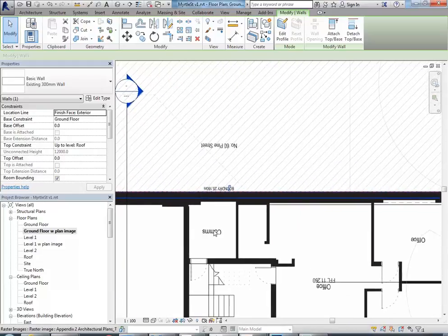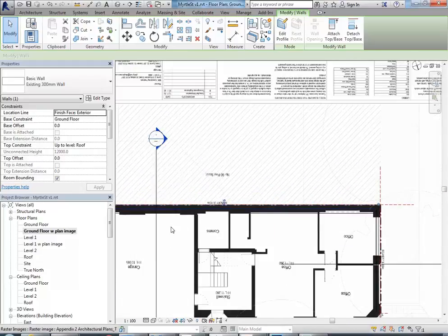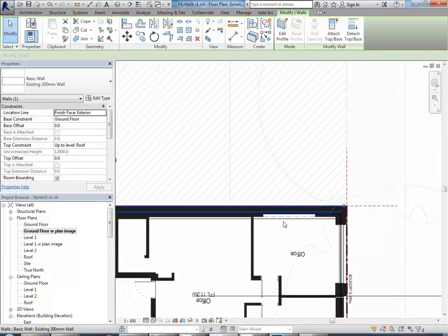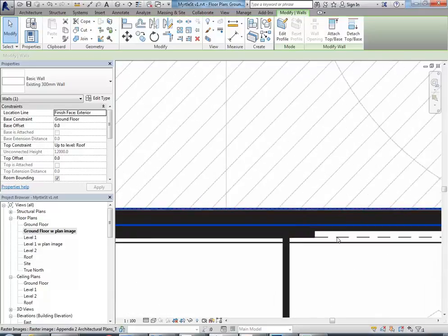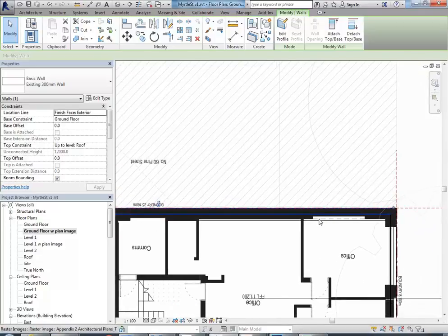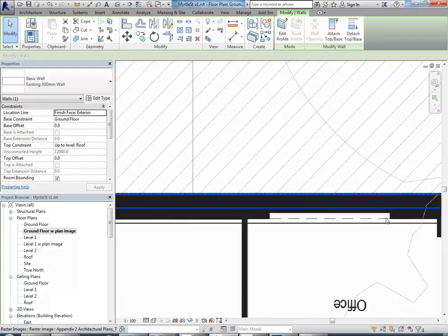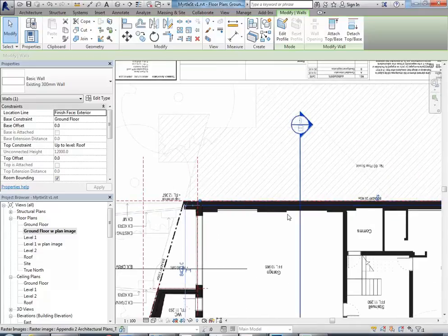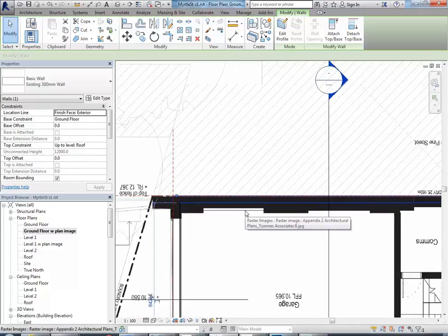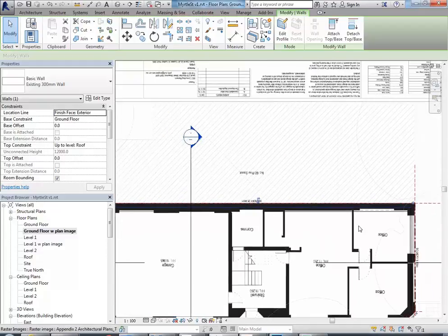Right, so looking at these alcoves here, what I'm looking for is the narrowest one. So it's this one, I'd be pretty sure. So again, you've got to make a decision here whether it's worth trying to put those alcoves in with the wall tool, or come back and chop them away afterwards. And I think that one is an alcove that is not the full height, so it's a recessed part of the wall. But we'll just ignore that and bring the wall out to here for that section. Over here, it's a bit of a tricky old wall actually. But that way, you can definitely do all of that.